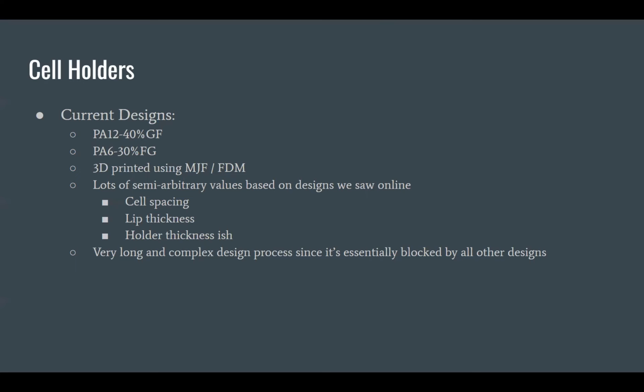And then as we went through our FEA, we were like, okay, cool. We tweaked, we refined, we changed things. But fundamentally, we started based on random. And rather than just going from an FEA driven approach, it may be better, because cell spacing affects the size of your pack quite significantly, to say, okay, well, let's have this be a parameter that we're tuning, not just in FEA after the fact, but especially during the initial pack sizing and pack layout.